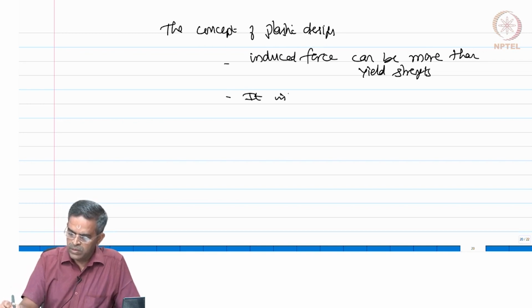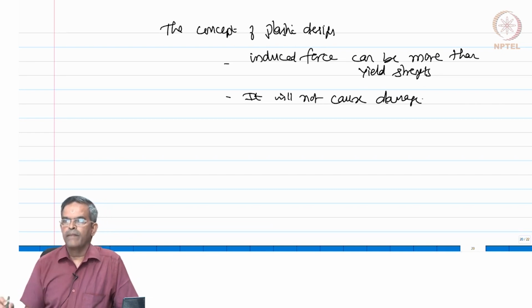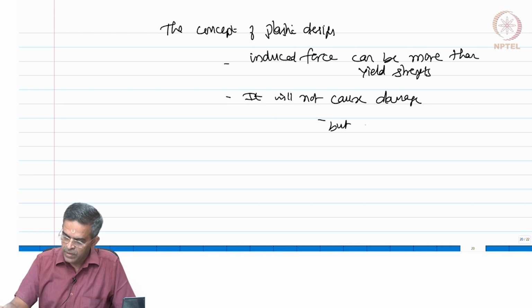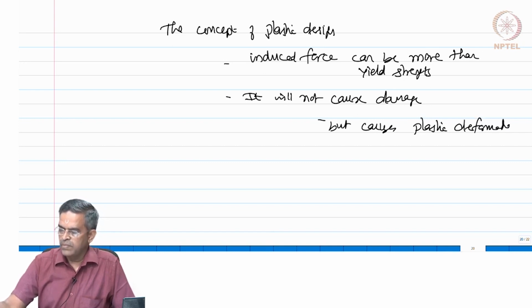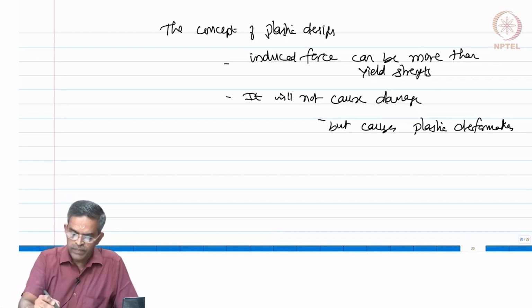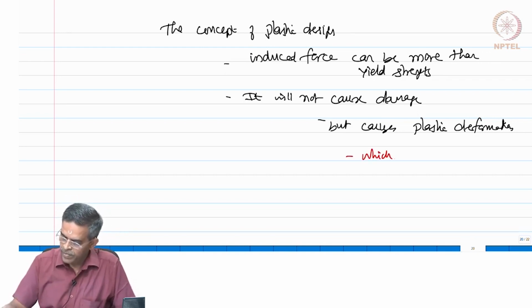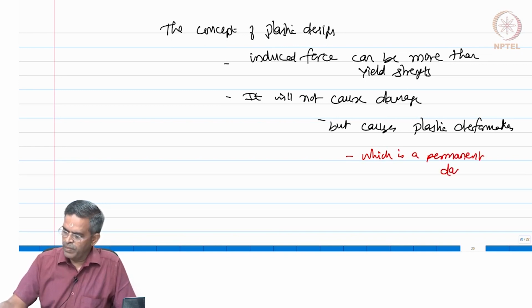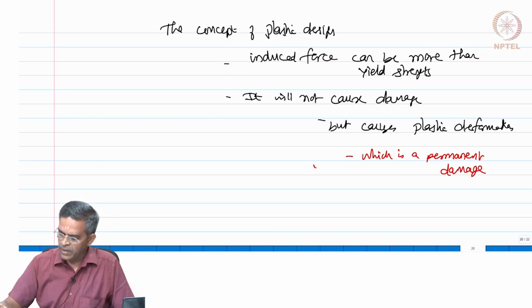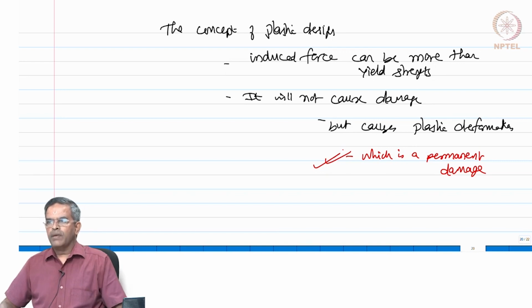It will not cause damage, but causes plastic deformation, which is a permanent damage. Please understand that. So, in plastic design, you are permitting a permanent damage. However, the force level will be much more than the yield strength of the material.